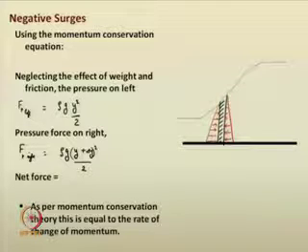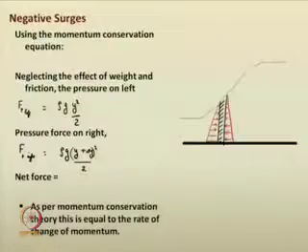For the net force, we are taking the frame as relative, where the frame also moves along with the velocity of the wave in that elemental strip, which is V w, right. So the frame is moving in that same direction. So we are suggesting that the net force is acting towards the left side, that is, opposite to the flow direction.